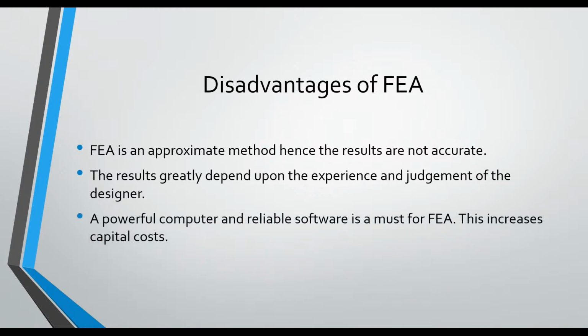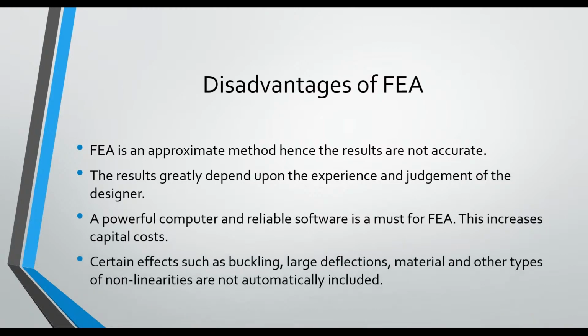A powerful computer and reliable software is a must for FEA. This is very important, and yes, it definitely requires a lot of investment. This increases the capital cost. Certain effects such as buckling, large deflections, material, and other types of non-linearities are not automatically included. This is just a disadvantage of the software, I would say. Maybe with time and effort, you will find that these results also get added, and new modules will come up and you'll find better results.